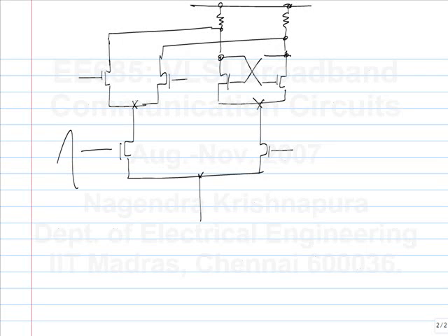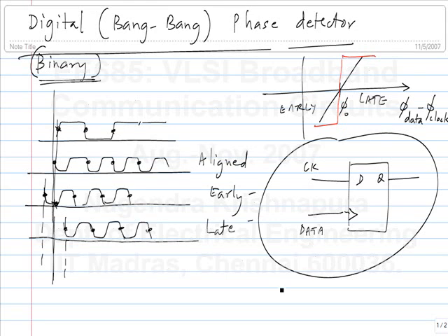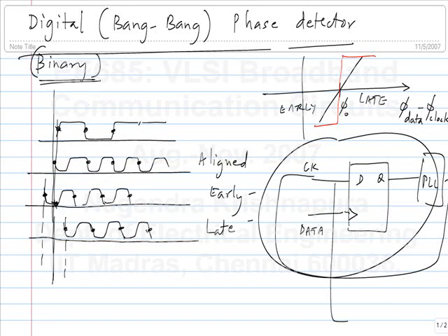Okay. So it just gives you the phase difference, but to sample the data, what you need to do is put this in a phase lock loop. Somehow you complete the PLL around it, and then you take another flip flop with the clock applied to clock and data to D and get the data out. Now, whenever you use different components like this, you end up with some mismatch errors, etc. So you would like the phase detector that you use, if it gives you the data itself, it will be better. Okay. But yeah, this phase detection works. So, how would you do that?